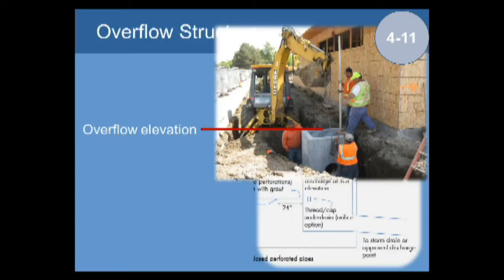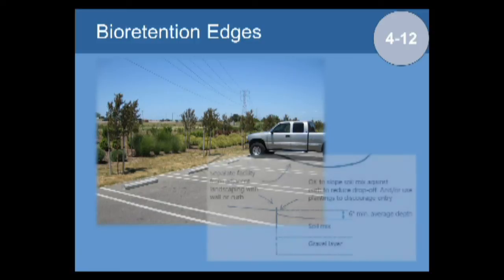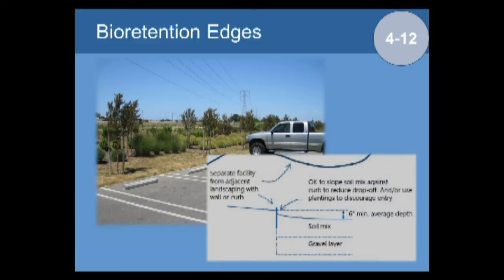It's one of the reasons that I think there is sort of a happy best size for a bioretention facility. I like to think that it's somewhere 800 to 1,000 square feet with the tributary area corresponding to that. That comes up with a good design, but certainly you see them a lot bigger and you sometimes see them smaller too. Bioretention edges. We put this into the guidance.